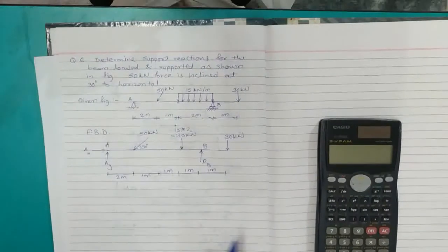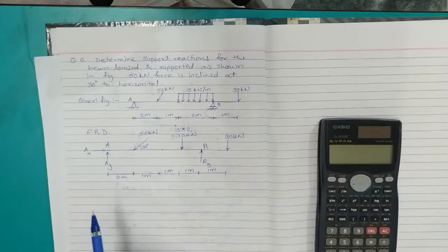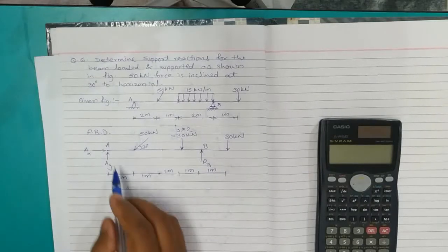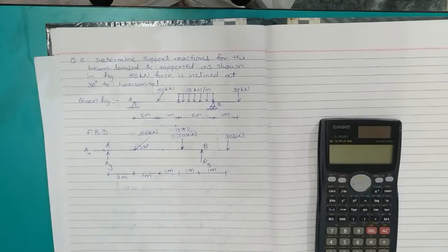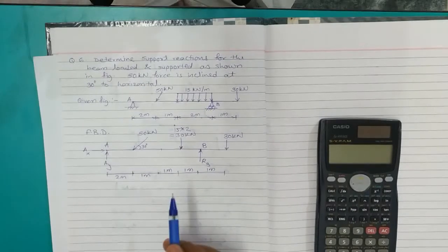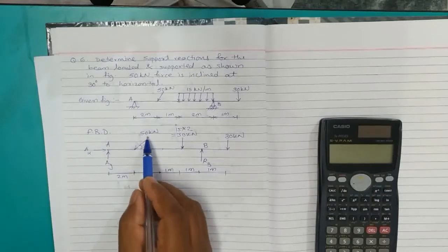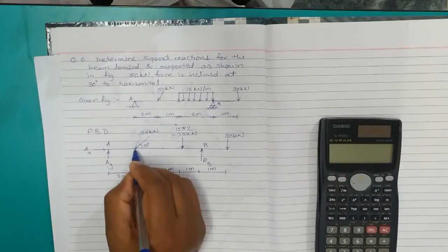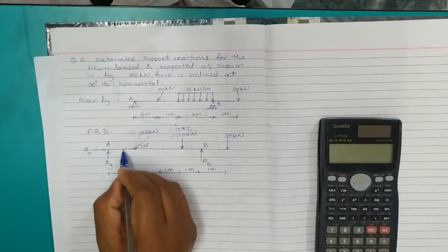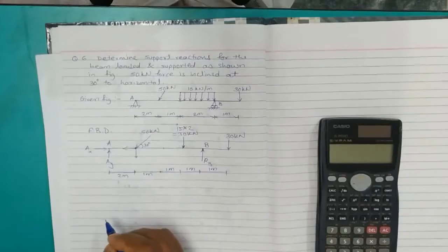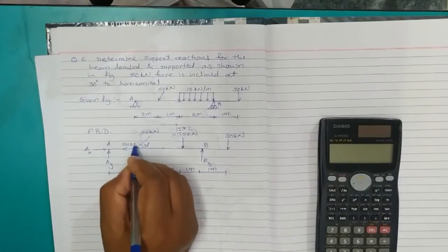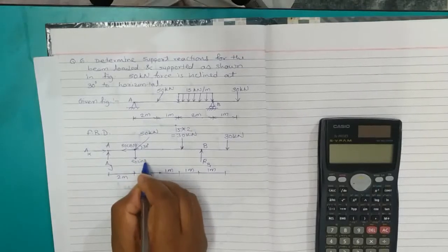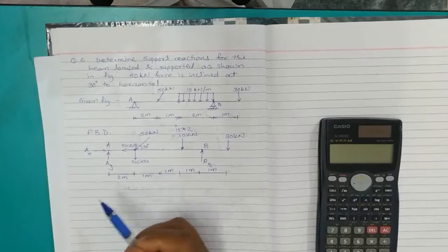Here also we have to use the same procedure. It is a non-concurrent force system under equilibrium. We have to use conditions of equilibrium and find out the unknowns. As usual, if at all you have a hinge point, always prefer the condition of moment about the hinge point and solve the remaining unknown, which is nothing but RB in our case. Here one very specific point we have to note down. 50 kilonewton is one inclined force, so we must resolve it, and the resolution has to be done at the point of application. If I resolve this 50 kilonewton force, the horizontal component is going to go left and the vertical component is going to go down. So we will have 50 cos 30 and 50 sin 30, these two components for the given inclined force 50 kilonewton.